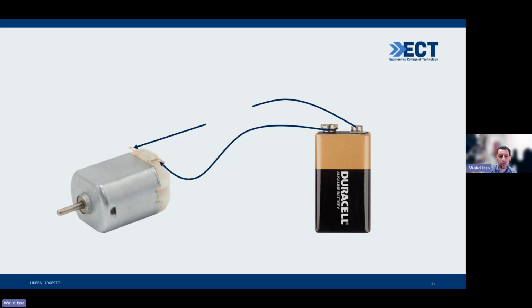And when you wire it like this, the motor will go to the top speed directly. What if I want to control that speed? I can put a resistor there. With that resistor, I can increase the resistance or decrease the resistance to make what? To make the current flow more or less. And that will make the speed higher or lower.